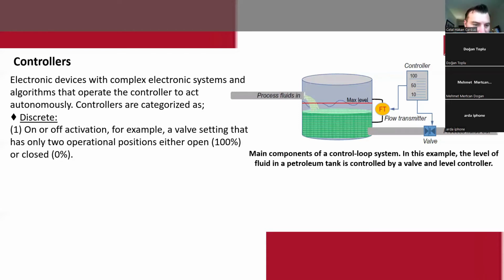This PCT is a kind of ball which is opening and closing. If it is in this position, the open part comes to the wellbore side, to the tubing side. Otherwise it's closed. When you communicate with it hydraulically and it opens, it's 100% open and flow comes directly. We could use that for just 25 times. It's one of the oldest valves that use the discrete methodology.